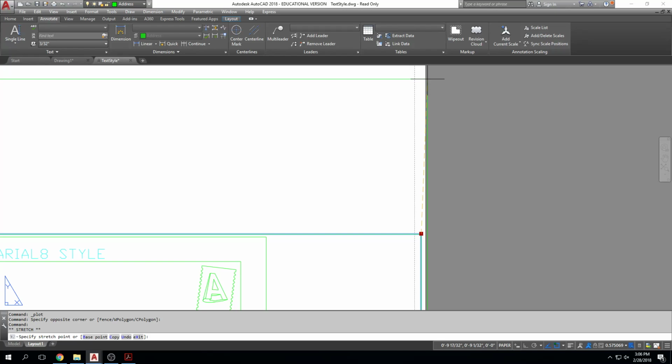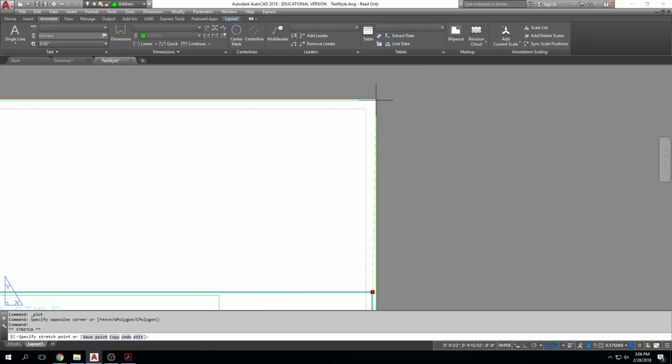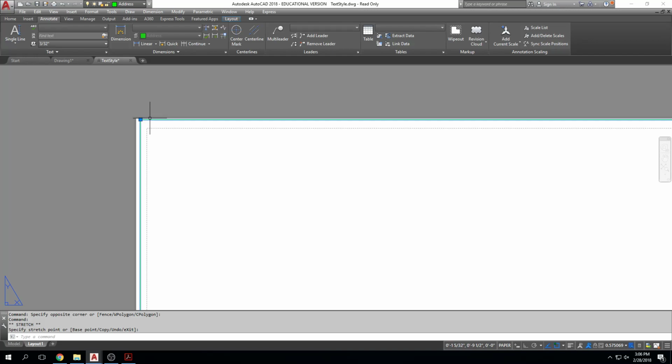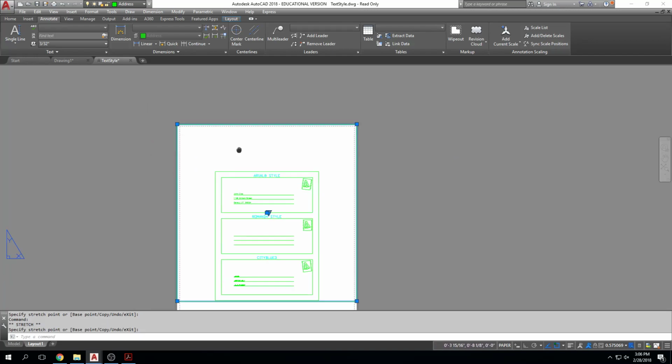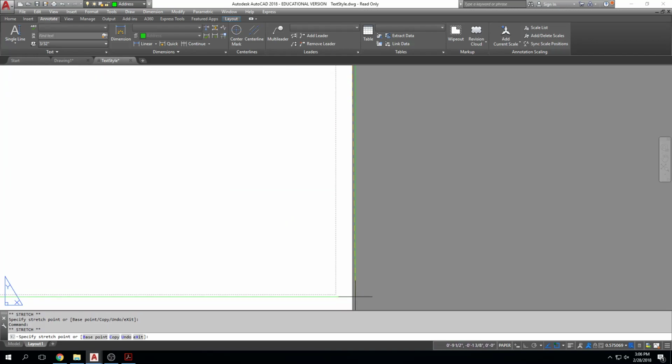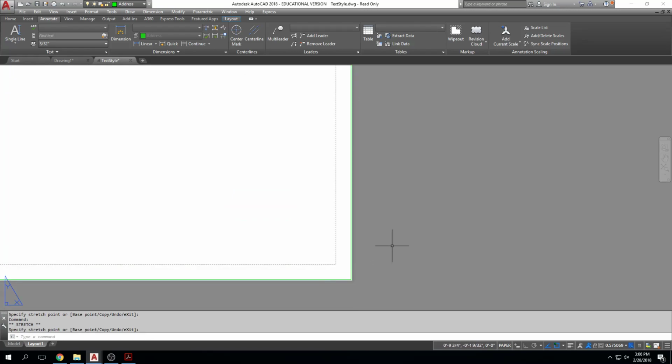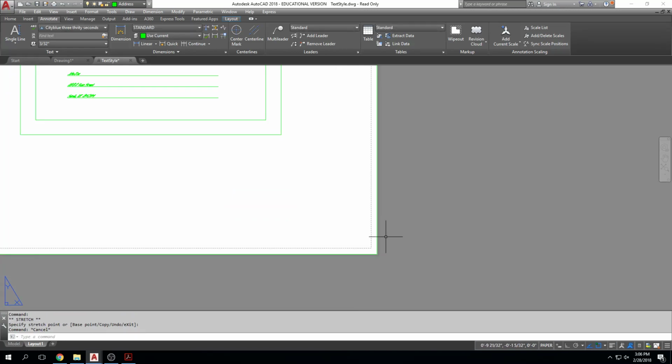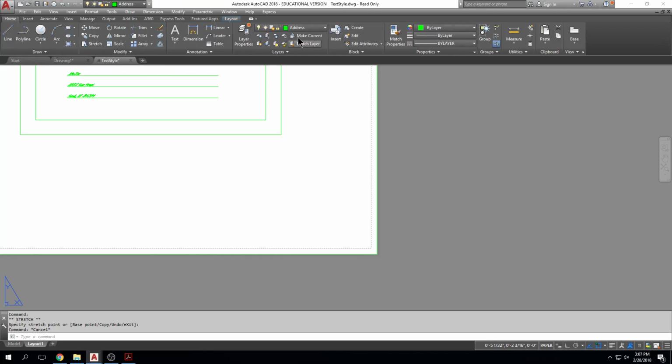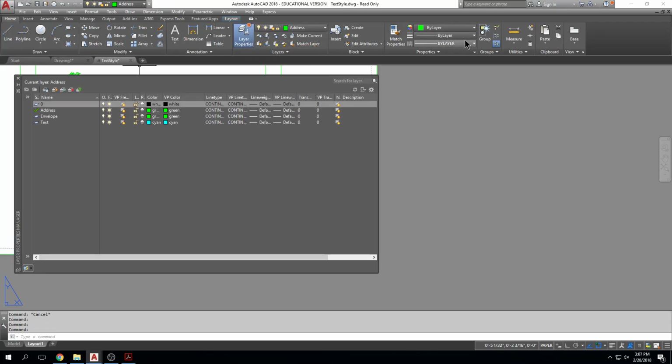Okay. So we're going to create a viewport here, and of course, I'm just going to drag this viewport, the default one. I'm going to drag it to the extent of my drawing here. Got a lot of steps, right? But so that my viewport doesn't print, I'm going to create a viewport layer that is non-printable. So, lots of steps. You'll remember these when you get moving in AutoCAD pretty well. I'm going to go to my layer properties. I'm going to click on new layer here.